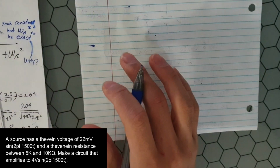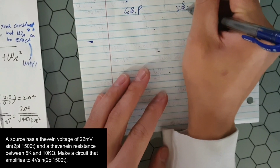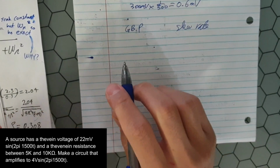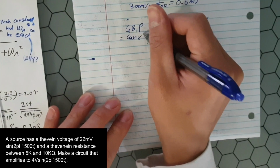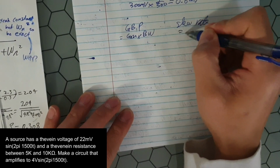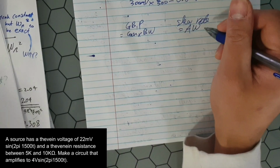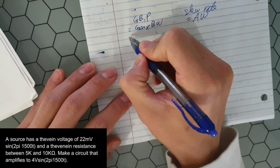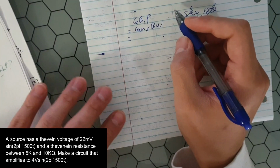So the first thing we need to do is check the GBP and slew rate. GBP is the gain bandwidth product, so it's literally just gain times bandwidth. And slew rate is the amplitude of the output times the frequency in radians per second. So let's check the gain bandwidth product first.